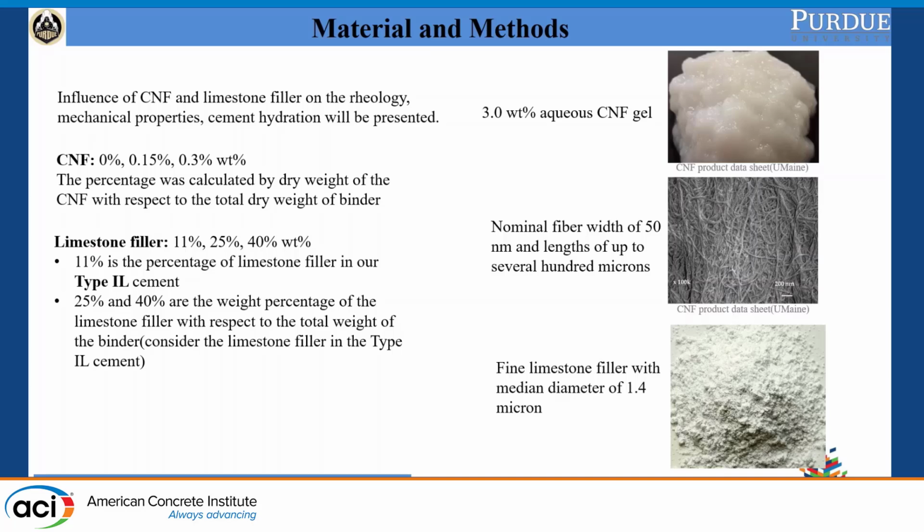However, as we just recently read, in Europe there's EN 197, which limits the limestone content to 35%. So we are also interested in how much increasing the limestone filler content affects the rheological or mechanical properties. Especially at this point, for 3D printing concrete, a lot of the applications are one-story or two-story buildings. We actually don't need super high performance for certain applications. So if we can maintain the overall mechanical and durability performance, we could reduce the amount of cement we are using.